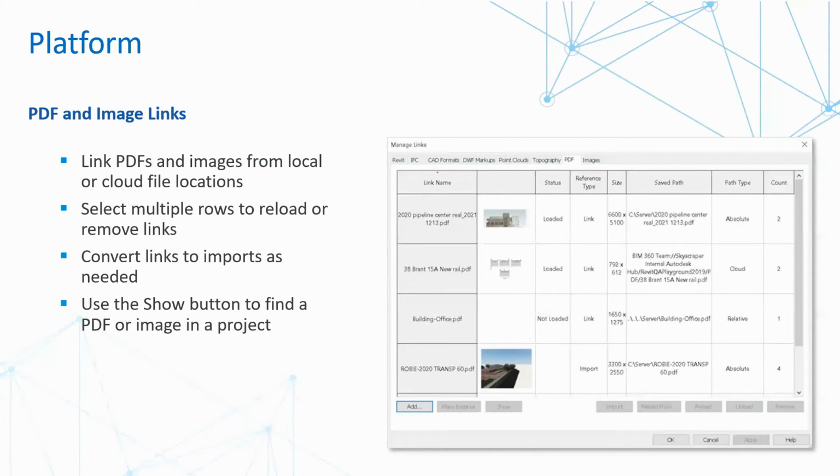Yes, that is correct. If you are looking for a specific PDF, you no longer have to filter through your project views. You can simply go to your managed links, select the link, and show it within the project.